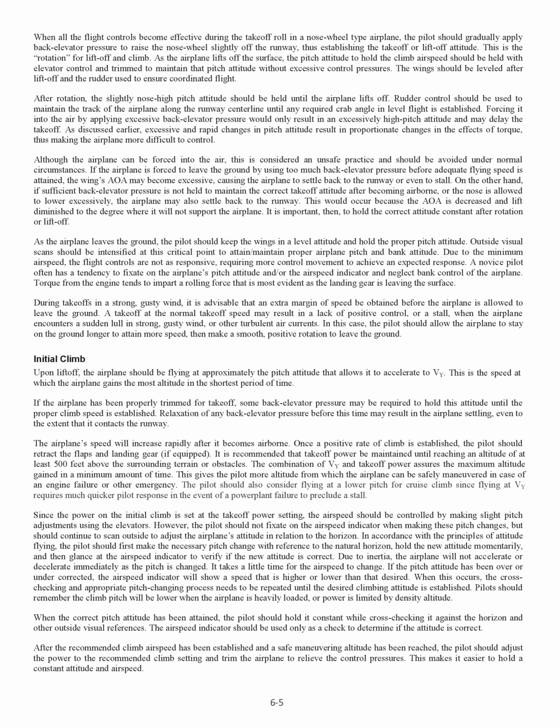As the airplane leaves the ground, the pilot should keep the wings in a level attitude and hold the proper pitch attitude. Outside visual scans should be intensified at this critical point to attain and maintain proper airplane pitch and bank attitude. Due to the minimum airspeed, the flight controls are not as responsive, requiring more control movement to achieve an expected response. A novice pilot often has a tendency to fixate on the airplane's pitch attitude and/or the airspeed indicator and neglect bank control of the airplane.